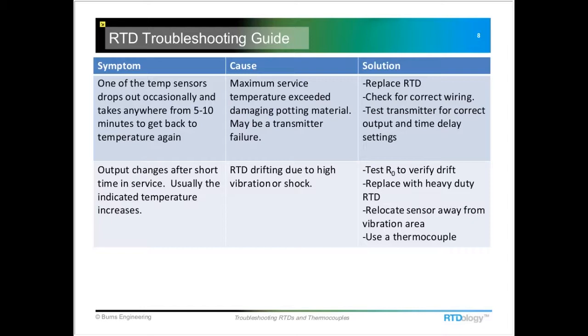We did a little bit of troubleshooting and found out the probe was okay, and it was connected to a transmitter also. We checked that, checked all the wiring, and all of that was okay. Eventually, the problem was found farther away from the system in another part of the measurement loop.